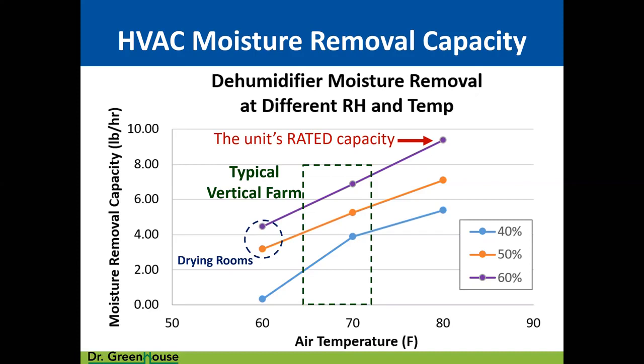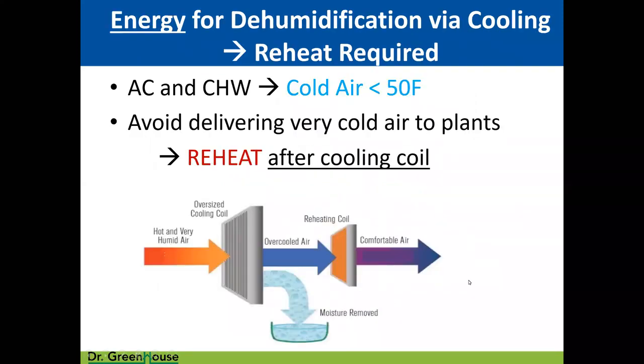And that's why a lot of you are having trouble with humidity control, even with dehumidification equipment dedicated to your facility, because you are assuming, and nobody told you otherwise, that what the equipment says it's going to do on its product sheet is what it's going to do, when in fact it's going to do half or a quarter of that rated capacity. And so you actually needed more of their equipment.